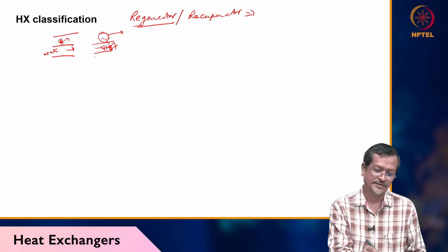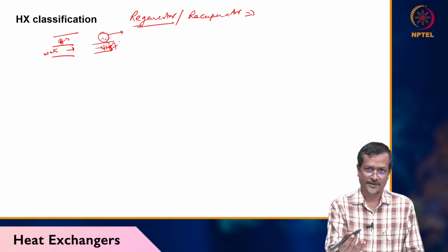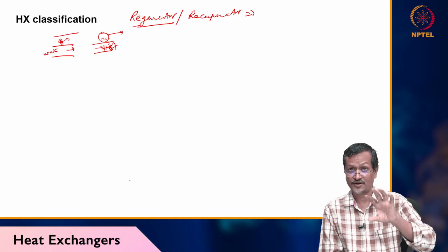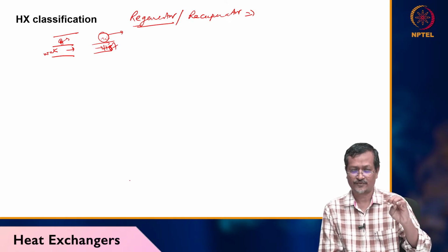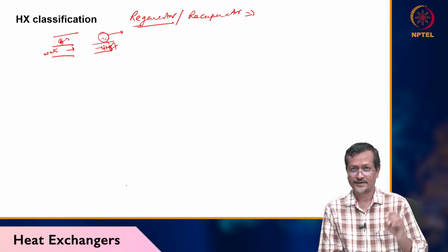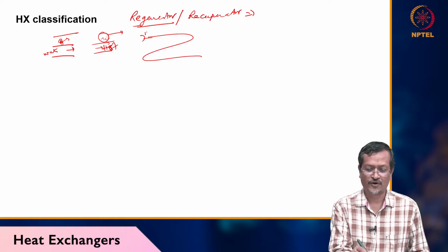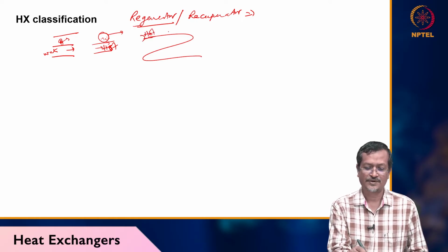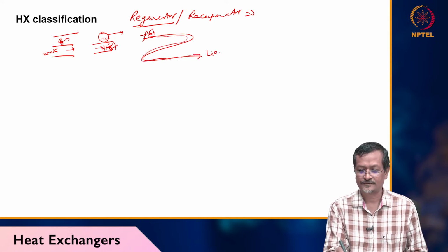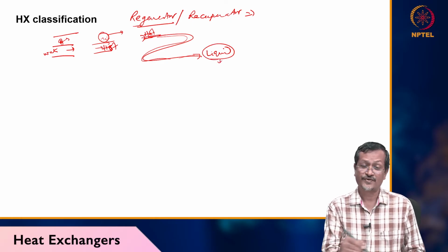So in two phase, evaporation is possible. In some cases you do condensation. Condensation means inside your refrigeration system, the condenser for a refrigerator, air conditioning system or cold storage system, the condenser part, the pipe will have hot gas or hot steam at the initial entry. After cooling here it will create liquid. So hot gas you are giving, liquid you are getting out. So phase change is occurring.